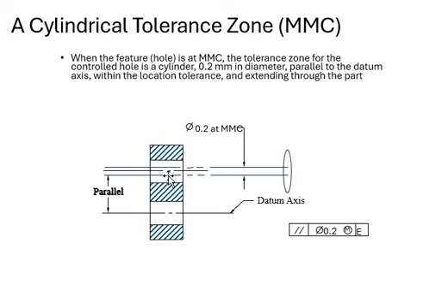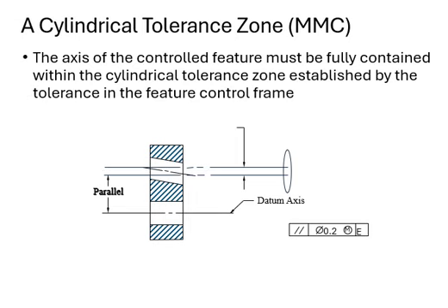And parallelism is right here that we try to measure, for verification processes or dimensioning processes, whatever you want to do, but definitely we want to get the distance from here to here, and we call that the parallelism. Of course, you're dealing with a cylindrical zone, and sometimes you're going to get variation in that zone like this. Some of the variations are good, some of the variations are bad, but try to make it as possible as you can to have your x's in that range.